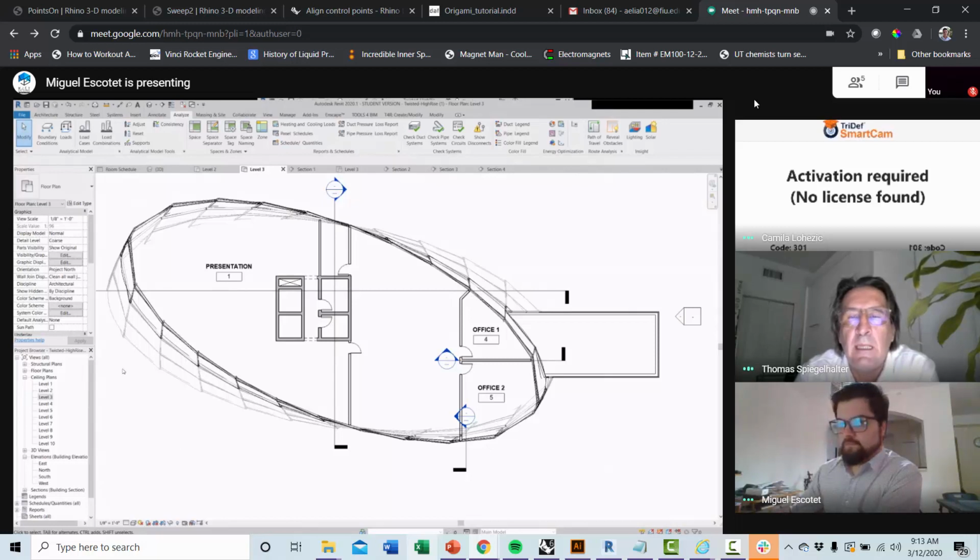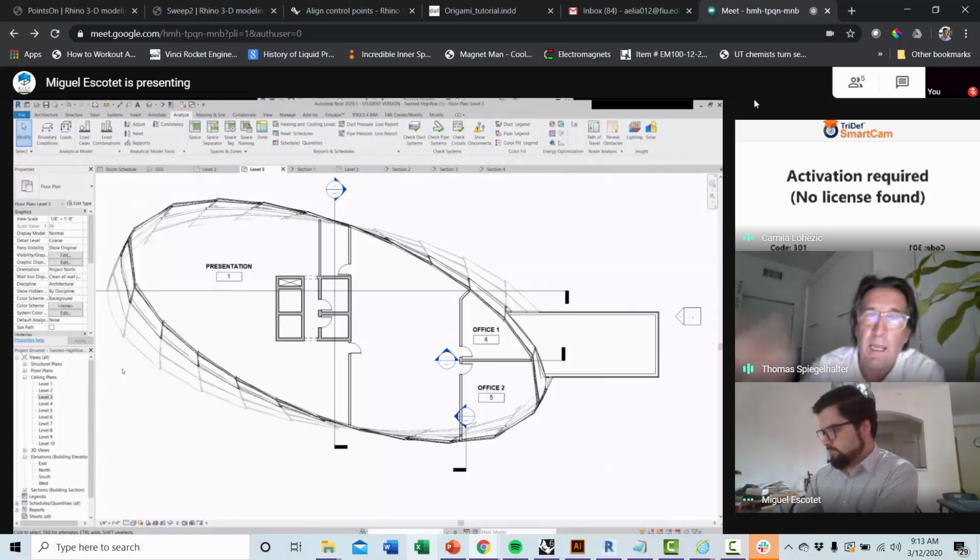This can now be further processed in the optimization tool, up in the energy optimization, and then sent to the cloud to update the GBS and the Insight. And when everyone goes to Insight360, then you will see where you are at that moment. Did you arrive already close to the carbon neutral benchmark standards of the AIA or not? If not, you can optimize the sliders in Insight360 with the recommendations, take a screenshot, note it, or make a report, and then go back to Revit, to the settings, and do exactly what